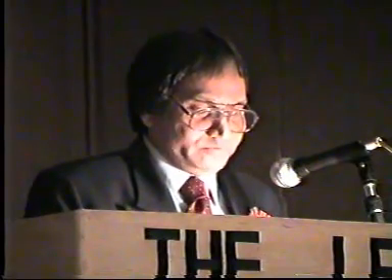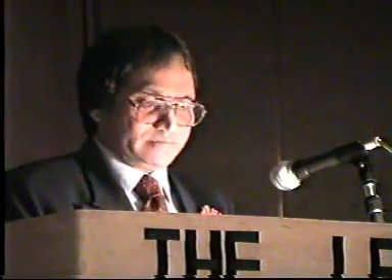It is often cumbersome for a chemist to arrange a glass assembly in the lab to start his work. Also, he has limited choice of selecting various types of stirrers for handling different consistencies of reaction mixtures. The glass assemblies prohibit working under a wide range of temperature variants. It is also difficult to get a cylindrical shape of glass reactors which may represent the shape of a normal SS reactor in a chemical plant. Quick heating and cooling is often difficult unless the heating mantle is first removed and a cooling bath is arranged under the reaction flask, and vice versa.